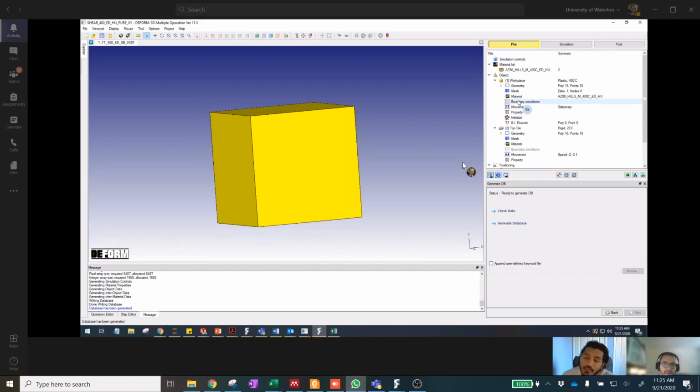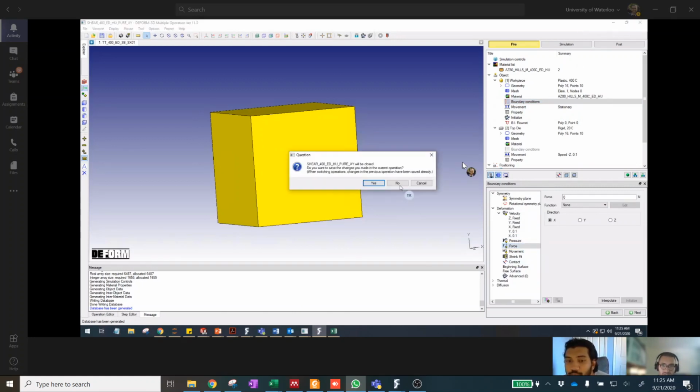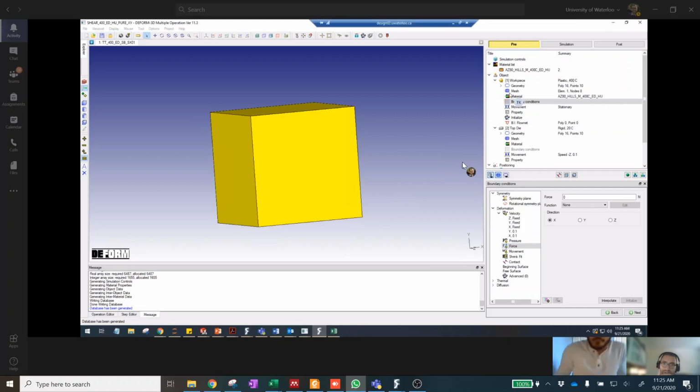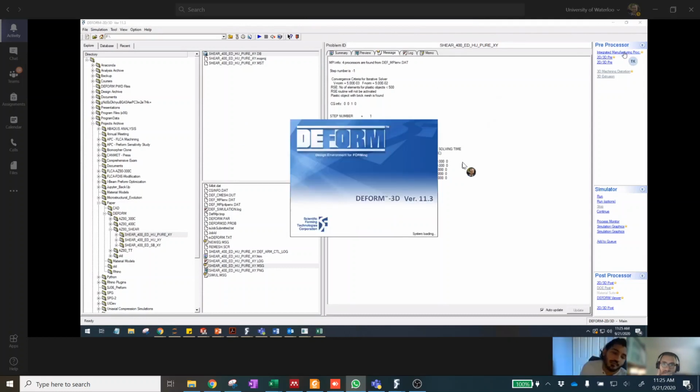Yeah. Okay. That makes sense. Maybe 1 newton of force. I don't know, because it's saying that the deformation is high. That's probably it, it's actually iterating and getting two or three iterations in, and it's dying because 10 newtons is probably way too much. Yeah, I think you're right. I think that is the issue.